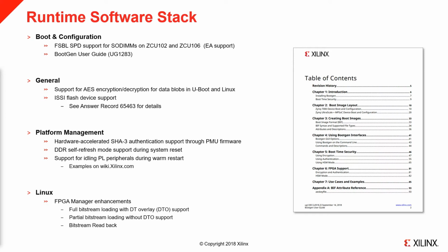The PMU firmware code for Zynq UltraScale+ devices has been updated to support several key new features. First, the PMU firmware now supports hardware acceleration of SHA-3 authentication via the xilsecure library. This change will improve the performance of applications leveraging the SHA-3 hardware in Zynq UltraScale+ MPSoC devices.